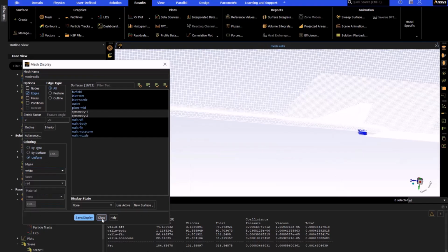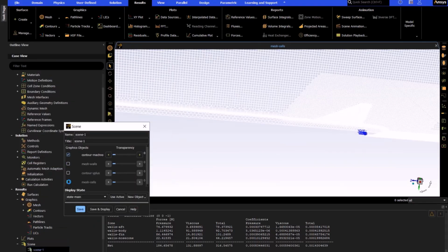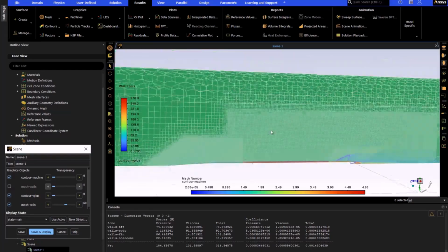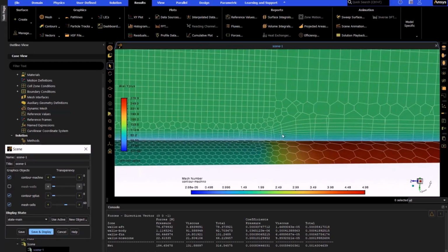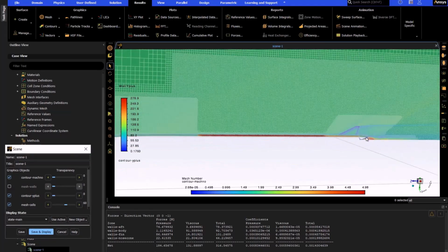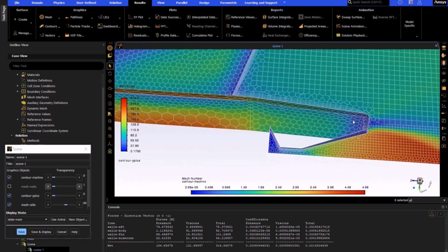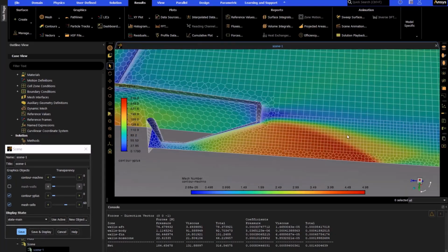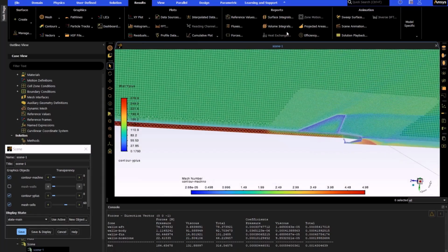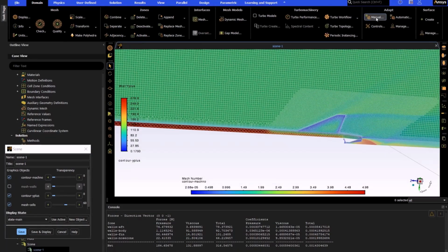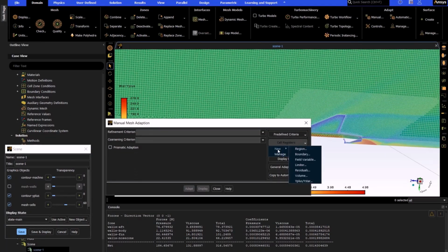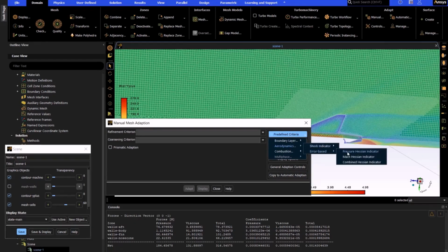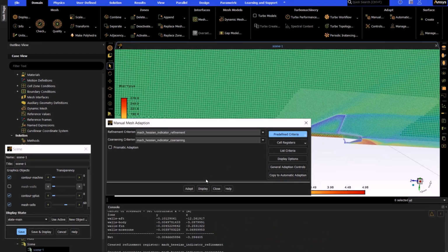Next, to check the flow field resolution, we can add the cell outline to our graphics scene. Here, we see the boundary layer cell's height increase where BOIs change, as well as some smearing in the shock structures of the exhaust velocity solution. To improve resolution, cell adaptation can be utilized under the Domain tab. Selecting Manual Adaptation and the Mach Hessian criteria will refine and coarsen the mesh structure where it exceeds gradient limits. These gradients can be set manually, but we'll just use the defaults.